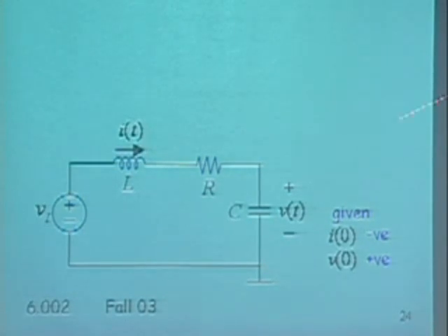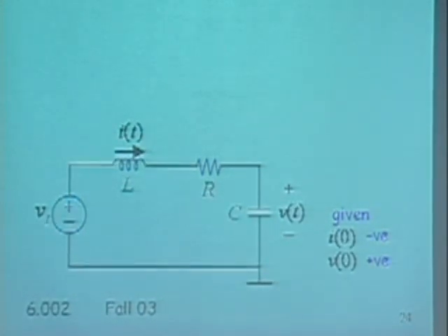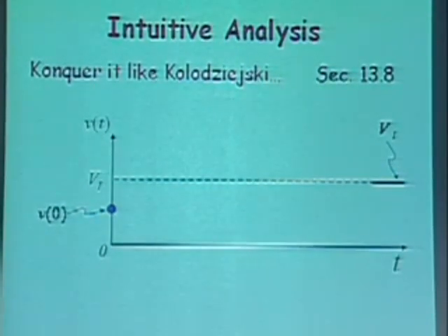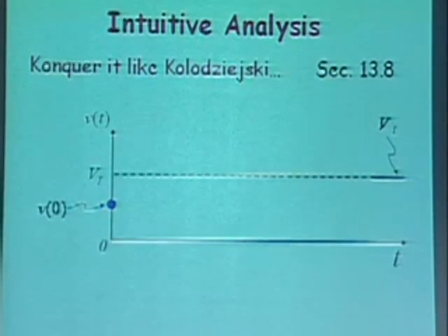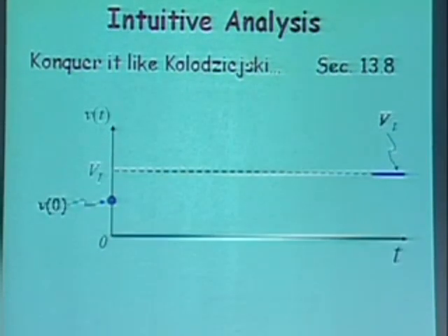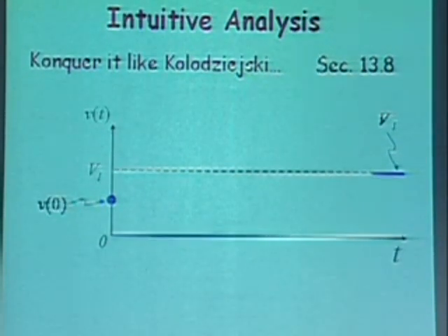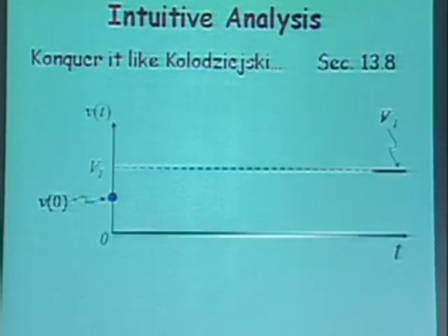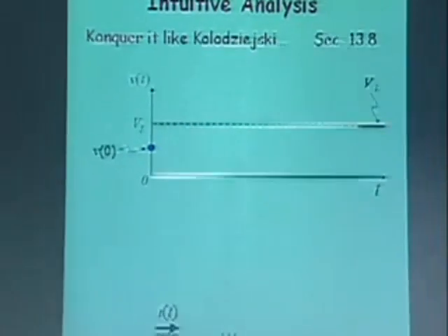I know the initial and the ending point of the curve. And then I know that somewhere in here there must be some funny gyrations. Remember, I'm dealing with the underdamped case. And you can determine that from alpha and omega naught. So if alpha is less than omega naught, you know that you are in the underdamped case, and this is what you get.